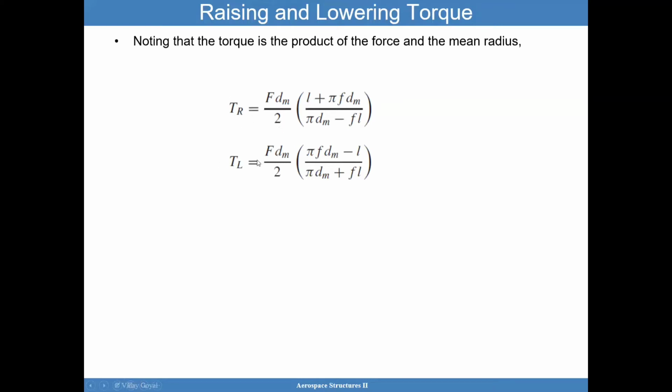And so what we've done here is we've shown how torque relates to the force that we want to lift or to lower that load. So we have a relationship that depends on the geometry and the load that we want to raise or lower. But in essence, what I'd like you to do is to pause the video and derive these equations on your own and go step by step and work it through.